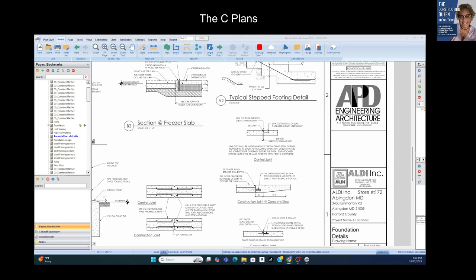You don't really need to know load information, but I've seen in a lot of situations where the shear wall nailing details aren't there, and they'll say similar framing with similar framing. Well, make sure you always get the detail. Similar to what? The exterior wall, the interior wall. Those are the things you want to get cleared up. It's probably overkill, but I think that's it.